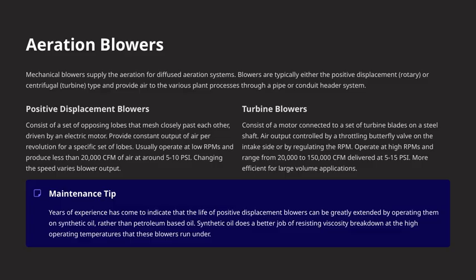Finally, a quick maintenance tip. Experience shows that the lifespan of positive displacement blowers can be significantly extended if we use synthetic oil rather than petroleum-based oil. Synthetic oil resists viscosity breakdown better, especially under the high operating temperatures these blowers often run at, helping to keep them running smoothly longer. Understanding these differences helps us choose the right blower for each application, ensuring efficient and reliable aeration across the plant.